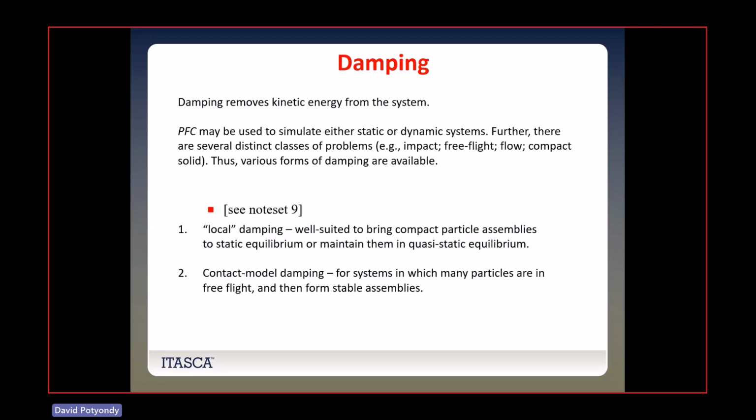And at any given instant, it's just vibrating back and forth in a certain direction, right? What I'm going to do is come up with a magical damping force, which is an additional force acting on the system that doesn't really exist, but it's going to be applied. And it's going to act against the direction of unbalanced force that mass feels. So we sum up the forces on a mass, and that's the direction it wants to start moving. And so we say, oh, you want to start moving this way? We're going to push against you.